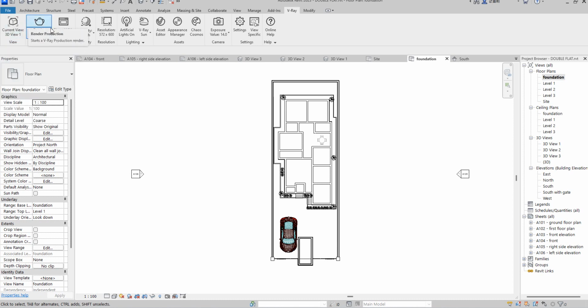The next thing is the production setting, the ready activities. Start V-Ray Vision on. If you want to render in cloud, but the most important thing you need is the production render. The next thing is the frame buffer dialog. That is where your picture is going to be showing. When you start rendering, this will pop up and you have it here. The quality is the kind of preset of the program you want. The higher the quality, the more the beauty and the details will come out.